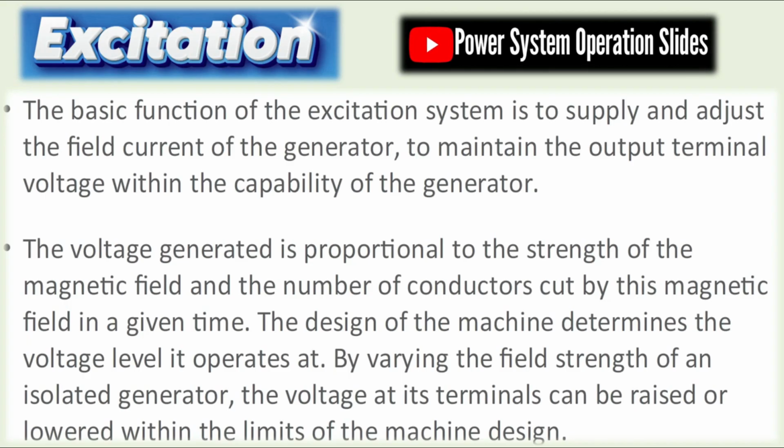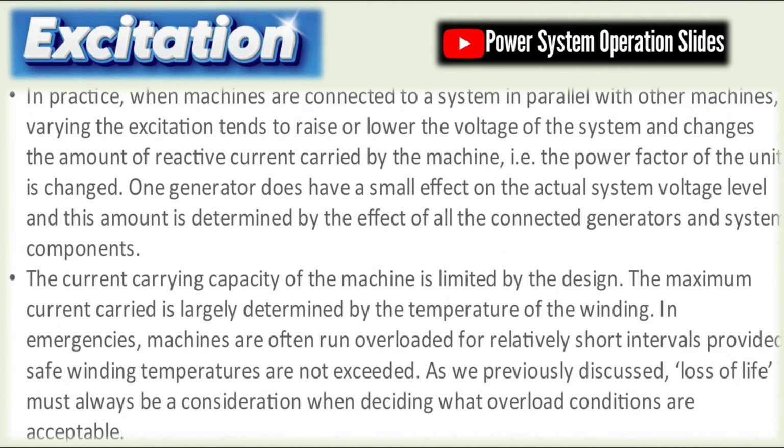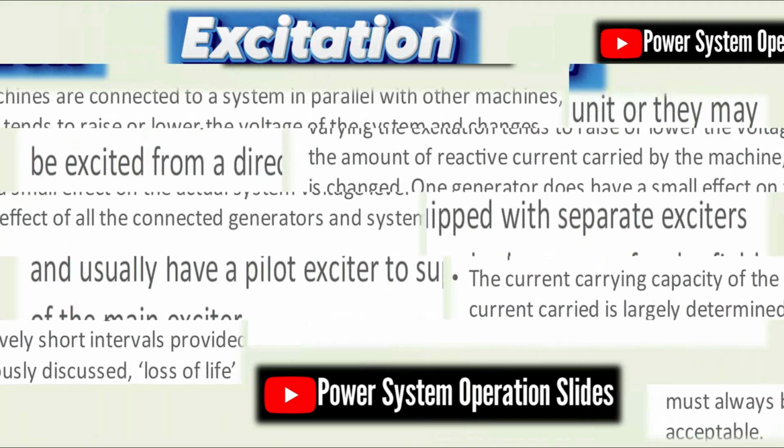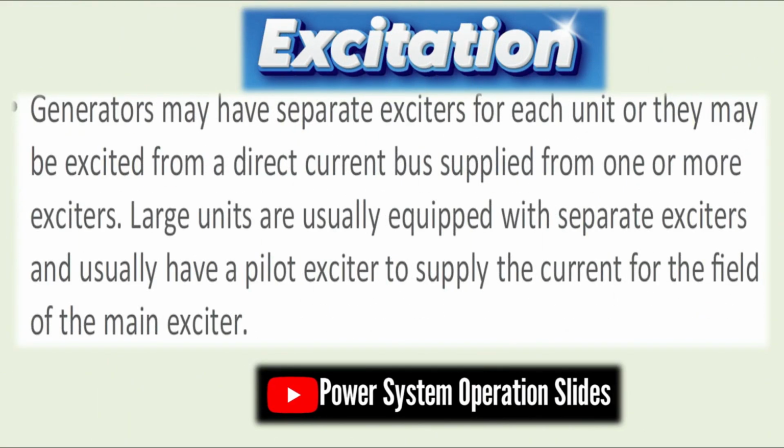Generator components. The stator is the stationary part containing the armature windings. Laminated electrical steel reduces eddy current losses. Slots hold copper conductors insulated with mica, epoxy, or advanced polymers. Cooling ducts are integrated for thermal regulation. Winding insulation ensures electrical separation between conductors and core. Insulation systems must withstand thermal, electrical, mechanical, and environmental stresses. Class F or H insulation materials are used in high-performance machines.